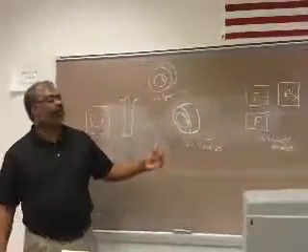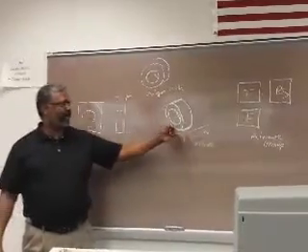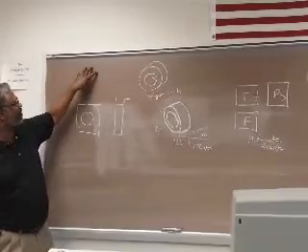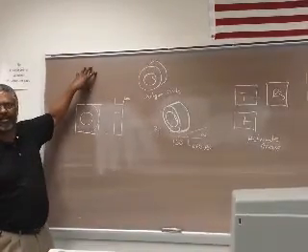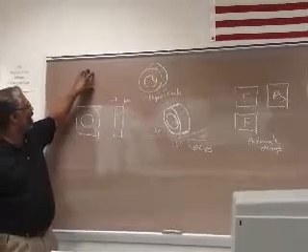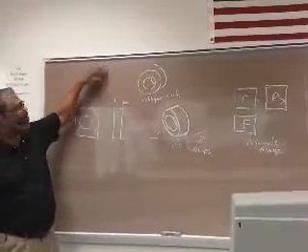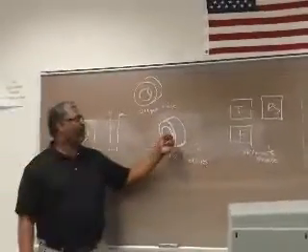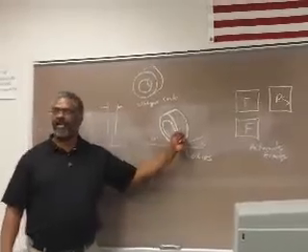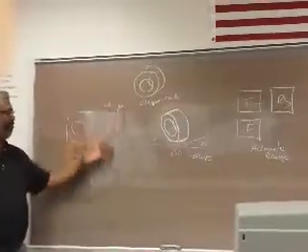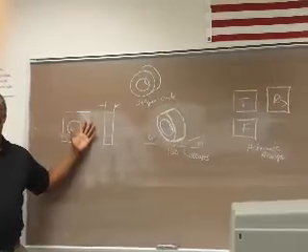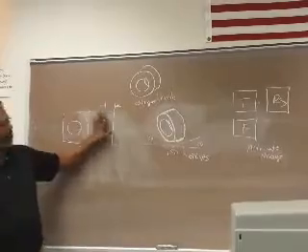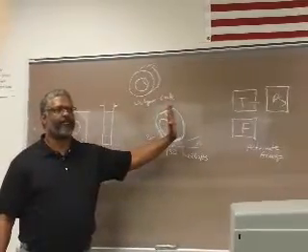Especially in CAD. Because in CAD, I could copy this to another portion of my drawing, and then copy this back at an angle, connect the lines, trim it out, and I got my oblique. Whereas here I have to set it up, I can't use any of the pre-existing dimensions on my object or any of my pre-existing views, because I can't take this and convert it to an isometric plane.